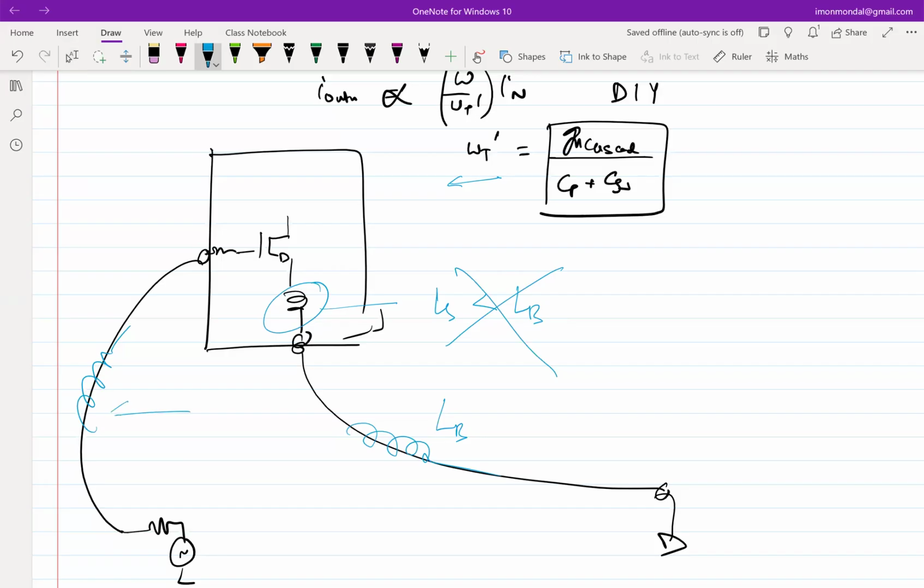Similarly, some packages give you very small bond wires, like half a millimeter of bond wire, like half a nanohenry of inductance. Then you say that I can go greedy, but the thing with those cases is that here I have neglected the resistance associated with this inductance, right?